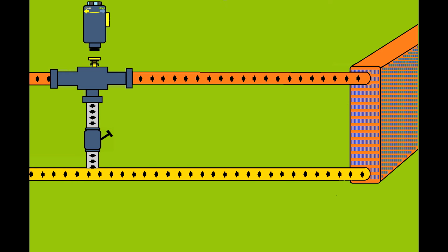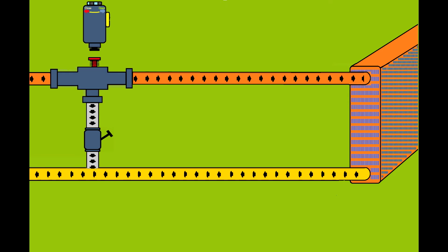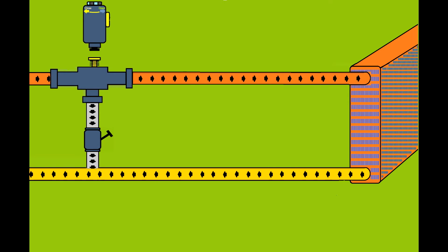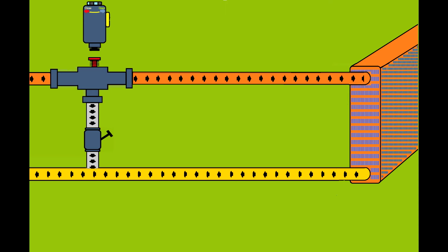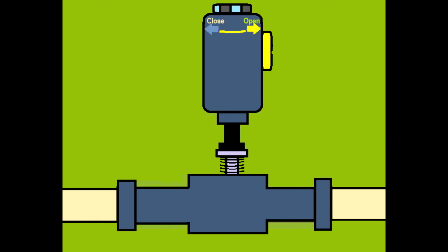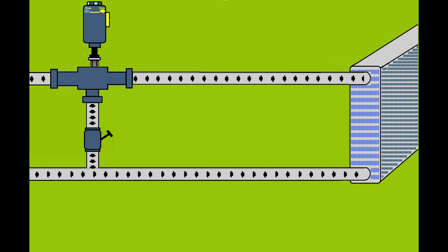So if you need more heat, you will open the valve 100%. Again, this is a fault. You see the valve has the shaft seized, and the entire quantity, a big flow of heating agent, passing by to hit the heat exchanger is seized at 100%. A good idea, as I said, is that the programmable logic controller, the BMS, will turn the valve off and on to 100% to clean the shaft, and then the faults will not be very likely to happen. This shaft will clean itself because the actuator will push it down to the limit and then release it.